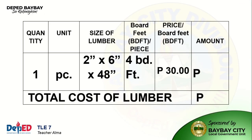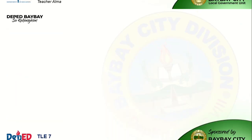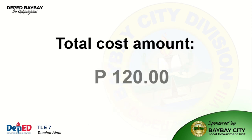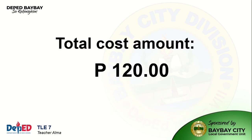To determine the total cost amount of lumber for problem number 1, if its quantity is 1 piece, with a size of 2 inches thick times 6 inches wide times 48 inches long, with total board feet of 4 and a price of 30 pesos per board feet, we simply multiply 30 pesos for price per board feet by 4 board feet per piece times 1 for its quantity, which equals 120 pesos. So the total cost amount for problem number 1 is 120 pesos.